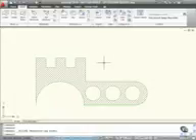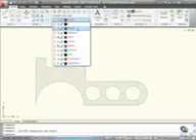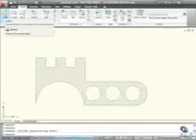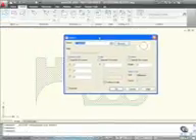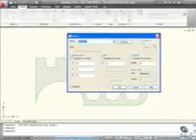No changes were made, so I didn't need to save any changes there. So that block has disappeared. But now, if I go Home tab, make sure I'm on my block layer here, which is a different color, and then go Insert Block here, or I could go Insert on the Insert tab. Either will do. What I need to find now is the actual block. There's my widget block there. It gives you a preview of it.